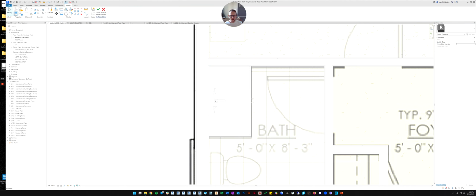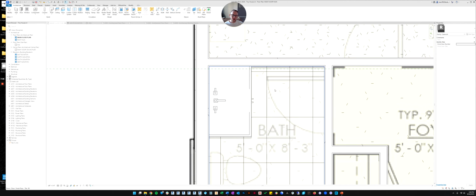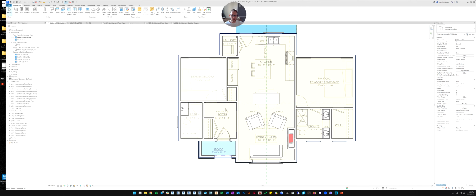And now you can see it kind of covered our sink, but it's still showing the faucet. So that's a good indication that we got it in the right spot. So now we've finished creating the extrusion. Now we need to finish creating the family, because in a family you could do a lot of extrusions in here, or you could do these other elements, but we're done. We just needed one extrusion to create our countertop. So we're going to hit finish model. And now it brings us back into our normal Revit model.